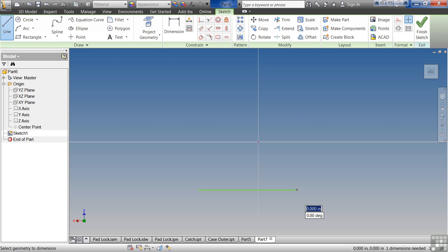If you hover over the end of the line, you'll notice I get a little gray dot there. Pick with my left mouse button and hold, and it converts it from a line to an arc. I get the glyph there at the bottom that tells me that it's tangent. Come up and I see my dotted line. That tells me the two ends of my arc are now vertically aligned. I let off my mouse button and I pull to the left. You see I get my tangent.